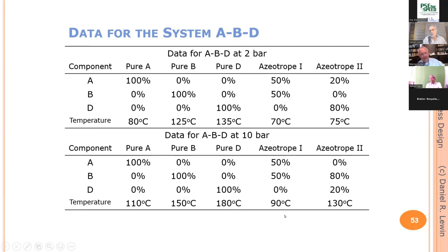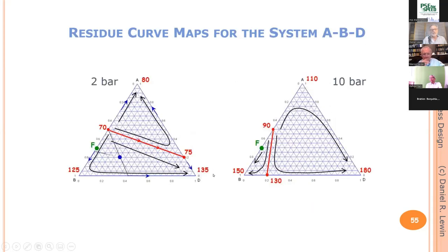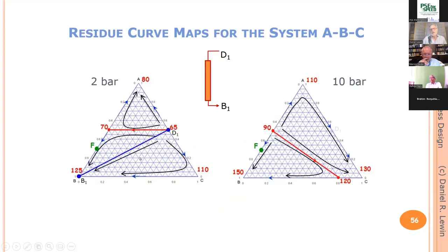Here is the situation for B. Of course, this column will be identical in both cases because it just describes the azeotrope that's giving us the headache. This is the reason why we can't produce 100% pure A and B. I'm not going to go into the details, but basically you eliminate the mass separating agent D because unfortunately it doesn't allow us to produce A at all, meaning that we go to C, and if we use the mass separating agent C, we see that it is very, very easy